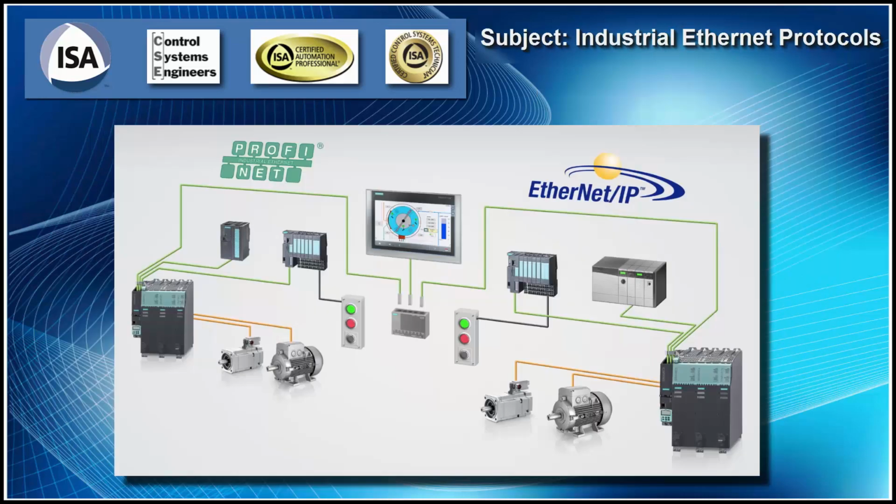Okay, when we're using Ethernet in industrial networks, it's only about 13, 15 years old. They haven't been used very long because they were not what's called deterministic. And in a control network, it has to be deterministic. That means that when we send our packets, they have to arrive within a certain time. And typically this is done by scheduling the traffic between your controllers and your I/O.